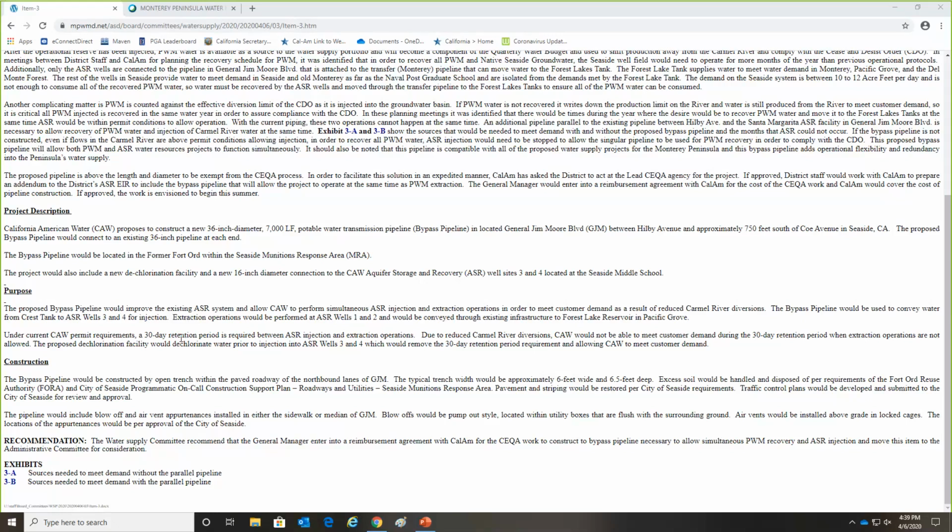At that point, the disinfection byproducts are below the Title 22 drinking water standards, and the water is then permitted by the Department of Drinking Water to be recovered. During the days before they go beneath the permitted concentrations, the water is being stored and is not permitted to be produced.